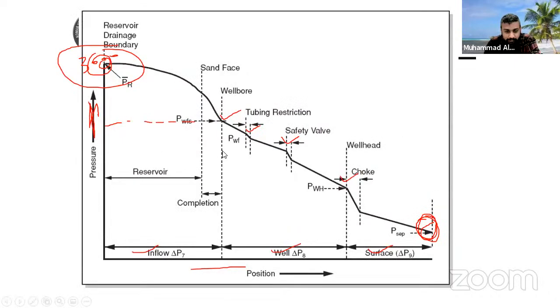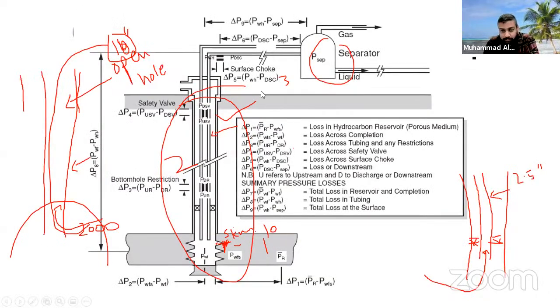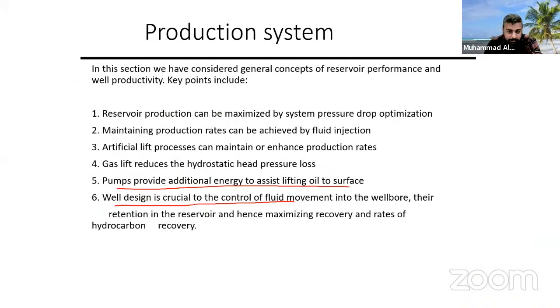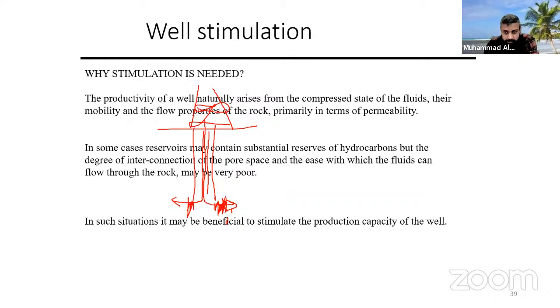Usually we use the coil tubing when we do this. So coil tubing is like when you water your garden trees at home, you use the plastic rubber pipes. So we have a coil tubing unit, and you're not sending the fracking fluid through this hard tubing string. No, we have a specialized truck, we call it a coil tubing unit. The coil tubing unit has a coiled, rubber tubing, which goes from this one to the bottom, and that is the one which is pumping the fluid and taking out the fluid at the same time. That's a specialized coil tubing unit that does this job.